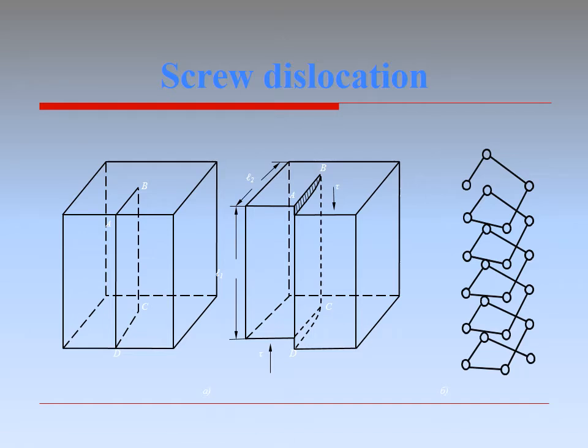The right dislocation and this the left dislocation. The main differences of screw dislocation from the edge ones. The first, screw dislocation is parallel to the shear, and the second, screw dislocation can be formed by a shift of any crystallographic plane containing the dislocation line on any surface ending with this line.